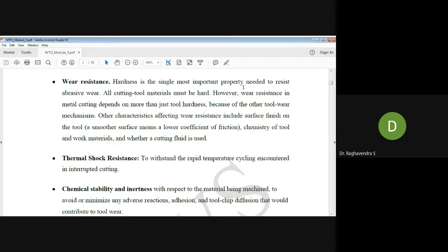because whenever there is a production process going on and there are changes in the cutting tool, we cannot achieve the desired geometry. The product dimensions will change. So that is the meaning of this. Whenever you choose the cutting tool material, it should have the wear resistance property.